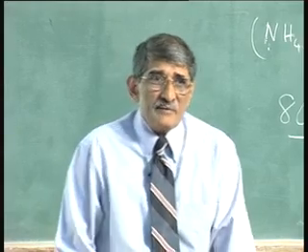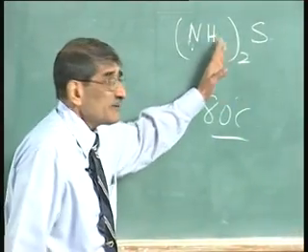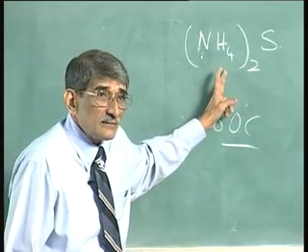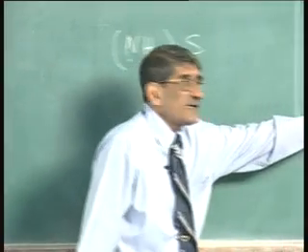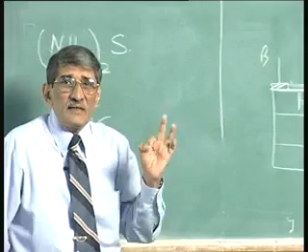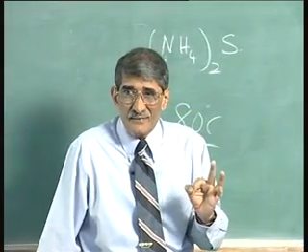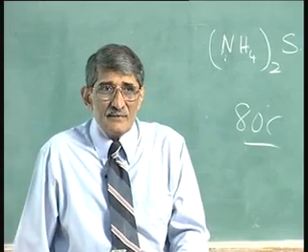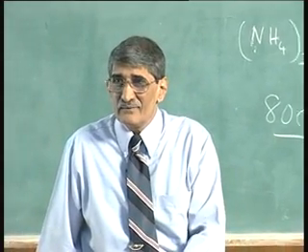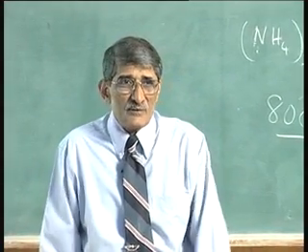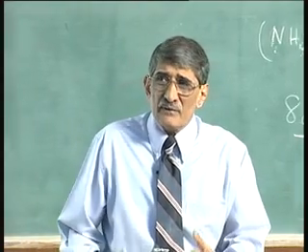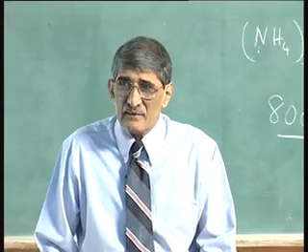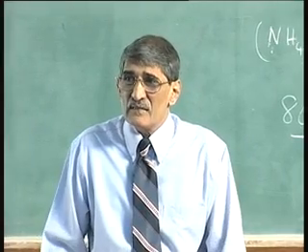The stability problem is because, as was found out little later, when you put this particular layer, the surface should be very clean. There should not be any oxide layer. Okay. If there is any oxide layer, then that oxide layer will react with gallium arsenide to release arsenic. That is what was happening. The surface recombination velocity was not as low as you want it to be. There is still a lot of recombination taking place, till they observed instabilities.